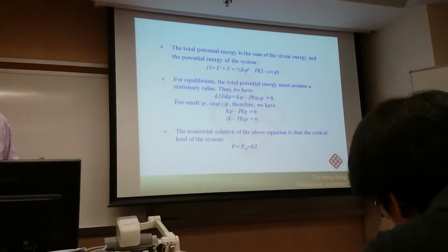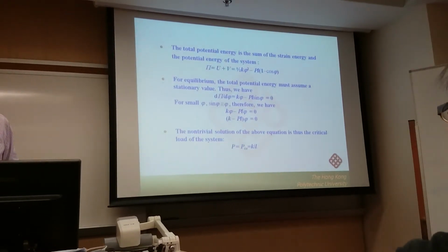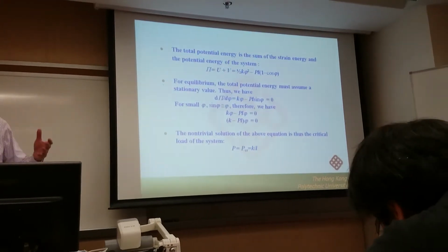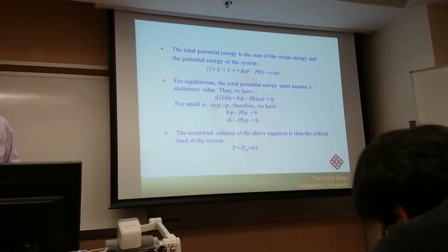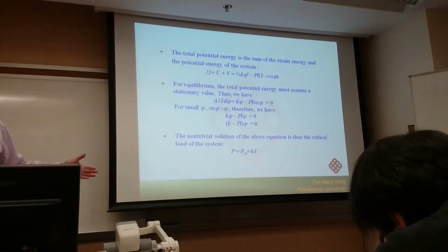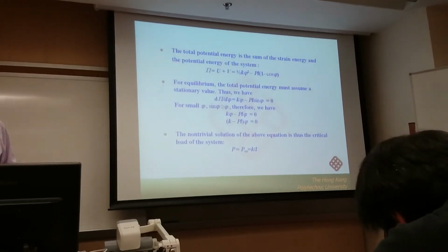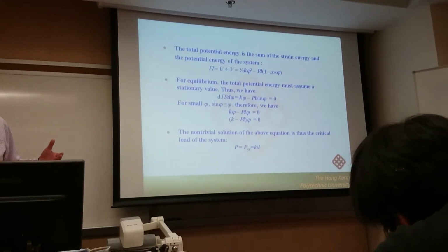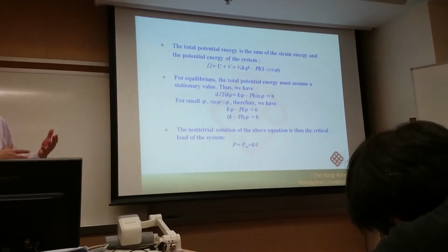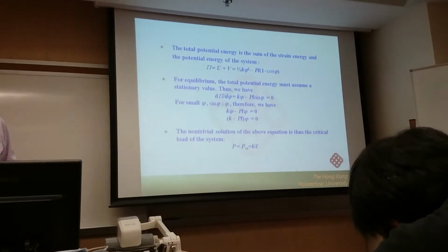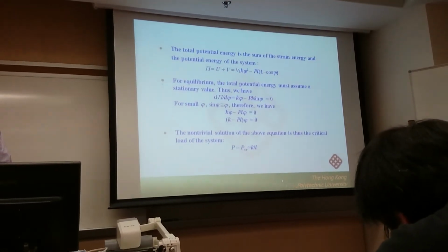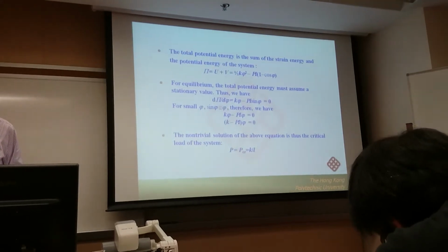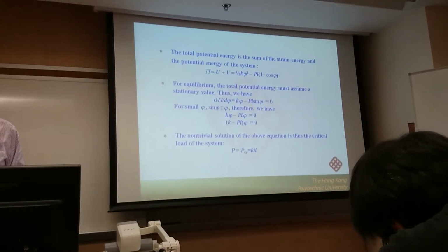The frequency is a natural behavior of structure, and also the critical load is a natural behavior of structure. When you have completed the design for a structure, the critical load is already there, like the frequency is already there. When you have built the building, the frequency is already there. So the critical load is just a function of the structural properties. It is independent of the response.